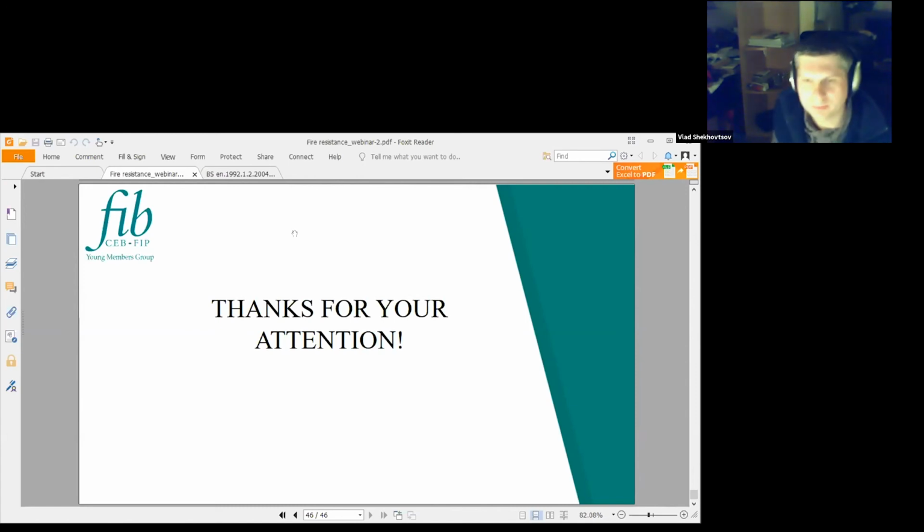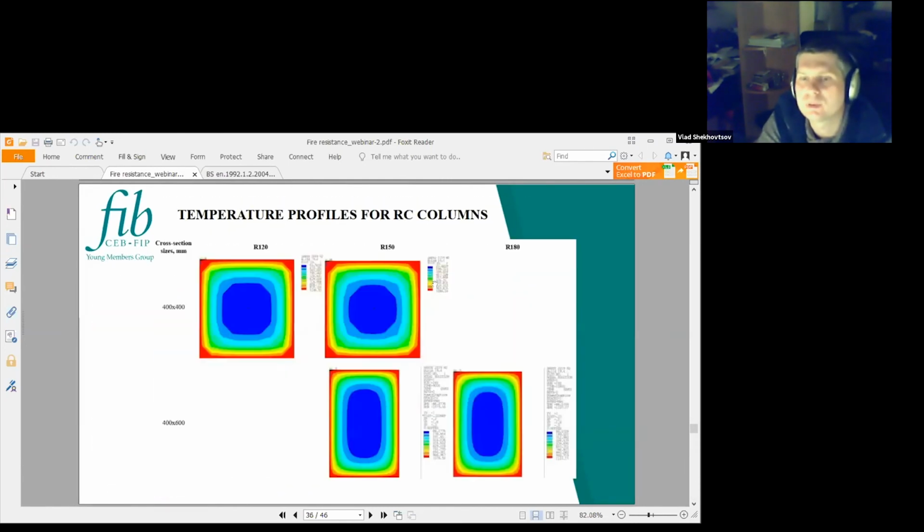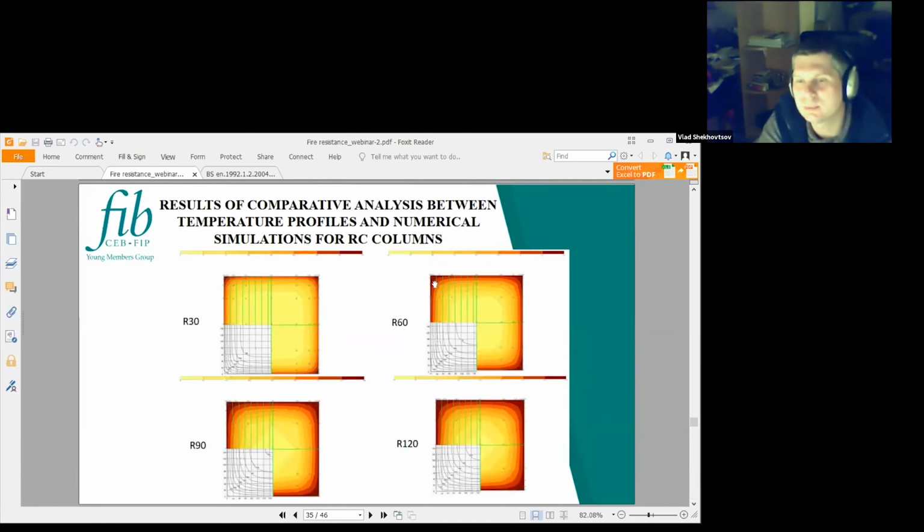We have ended the questions from our participants, but I still have my questions. So if you don't mind, I will ask you. My question is about the results of your numerical analysis. On these results, no results were seen in the reinforced concrete columns or concrete columns about the temperature. The digits were too low, so I ask you to tell me what is the temperature inside the sections at the places where the reinforcement is usually located. I don't clearly understand if you have calculations about reinforced or only concrete elements. But it is interesting what is the temperature in the places where we situate the reinforcement.